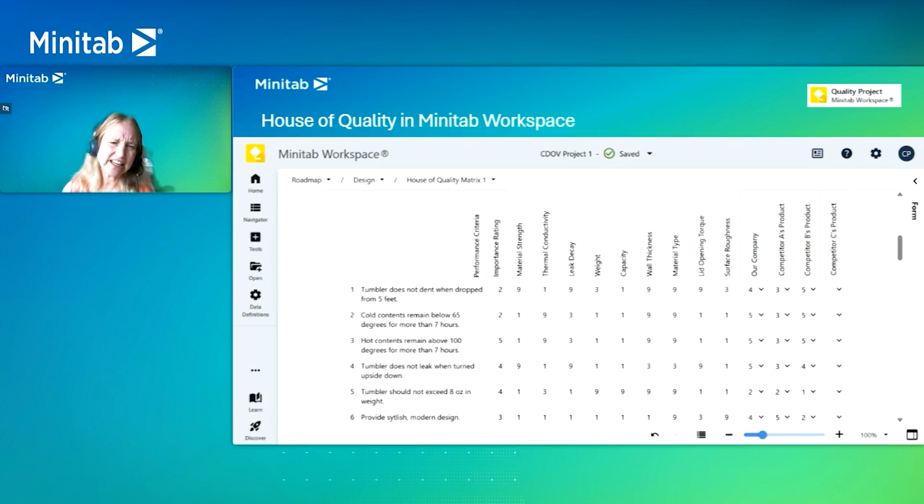So looking at more detail, there are actually 3 houses of quality. We're going to focus on house of quality 1. Now, you should recognize what you see down here. Again, this has been automatically populated. These were the specific measurable requirements that came in from the customer. We saw these when we did the voice of the customer summary, as well as when we prioritized them. Based on the priorities we got when we did the pairwise comparison matrix, we can rate them in terms of their importance. And then what we do is we set out to create design parameters or performance criteria in terms of our design, right?